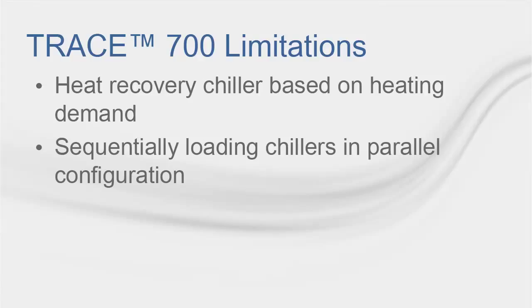Additionally, if you are looking to sequentially load chillers in a parallel configuration, Trace is unable to model this scenario. The parallel or parallel decoupled configurations only operate as previously discussed, with the chillers operating in tandem and ramping up and down to share the load.